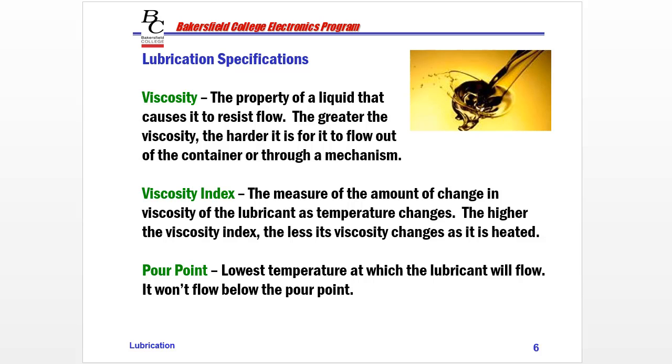And then other times we need a lot thinner material. Generally, when the machine is operating at high speeds, we need a thinner viscosity than when it's running at low speeds. Temperature also has a factor as well.